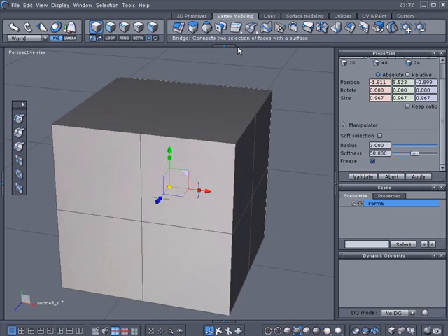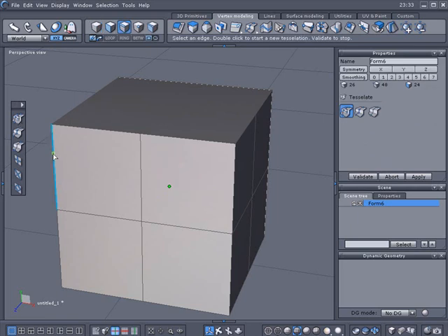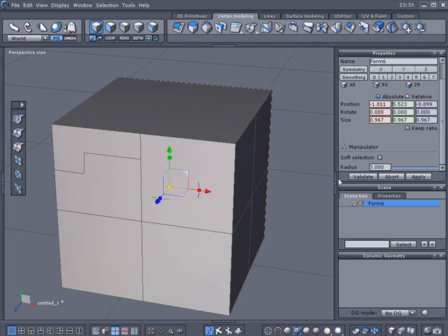I had paused the video and I got these more in the Tessellate icons, and I loaded them over here while I had the video paused. And we'll start with a free Tessellate. It must start on the edge and end on the edge. We can click here. We can click in the middle of the face here, and it must end on the edge. Then we'll go to the next one.